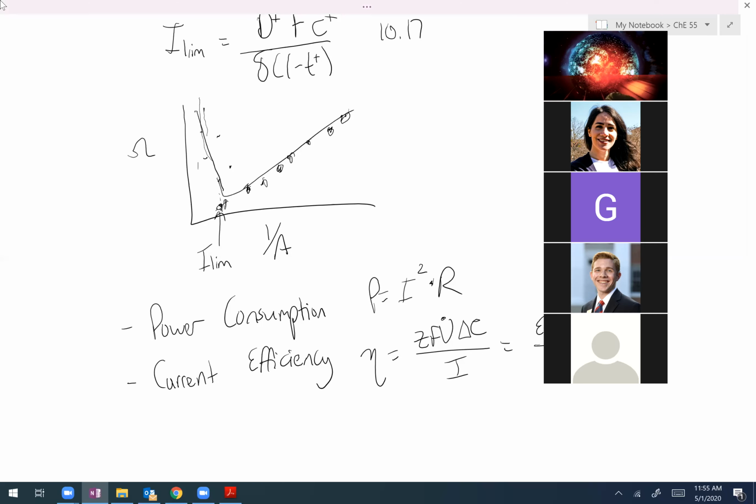And when you have water splitting in your system, you're going to have vapor. The electrical resistance of water vapor within your cell is going to be orders of magnitude higher than the liquid within your system. That's a big part of why the resistance starts shooting way high. So you look for the inflection, and that gives you your barrier or your limiting current, in terms of don't operate beyond here, because essentially you lose Ohm's law due to all those secondary processes.